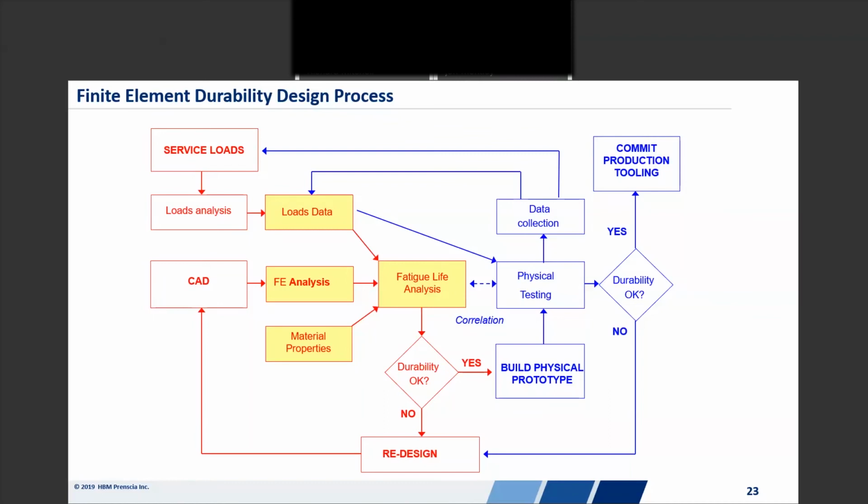If we don't, we go back in, redesign the part, and reanalyze. We go through this sequence until we come up with a design that I can put on a test and it won't break immediately, it won't live forever, but it's going to sit in that regime where I have the target life I'm trying to design for.